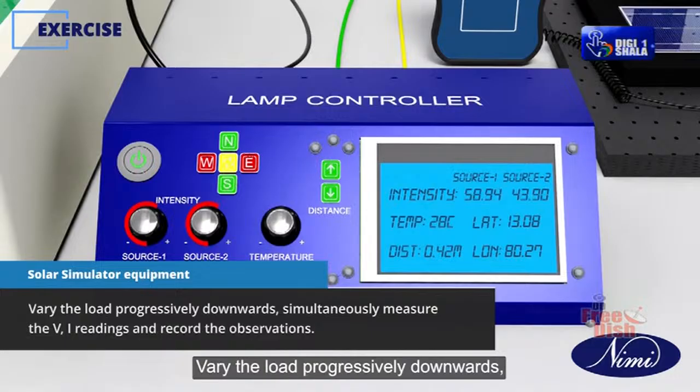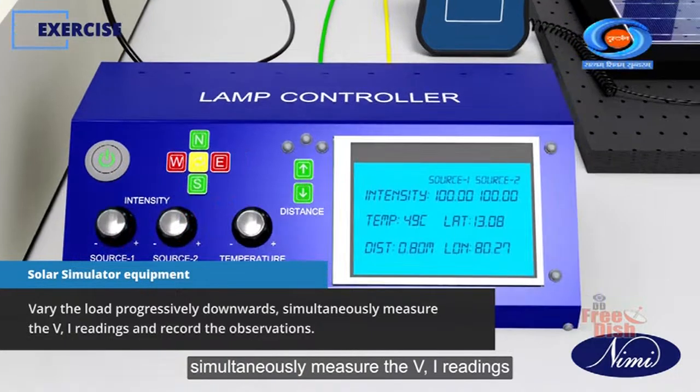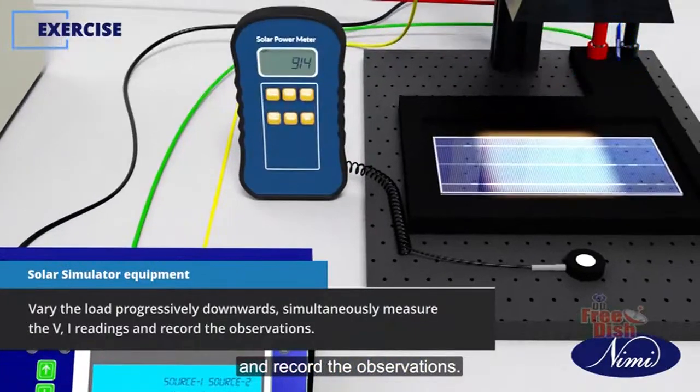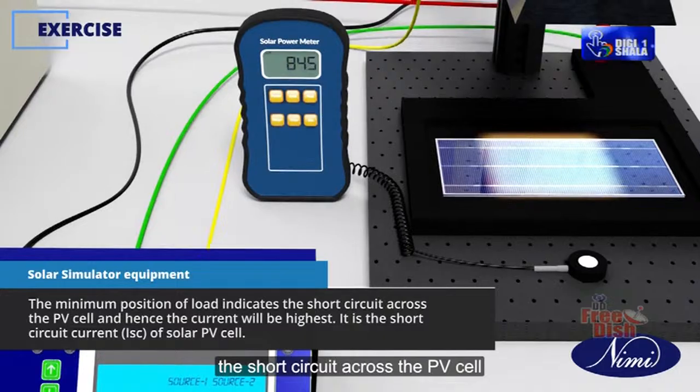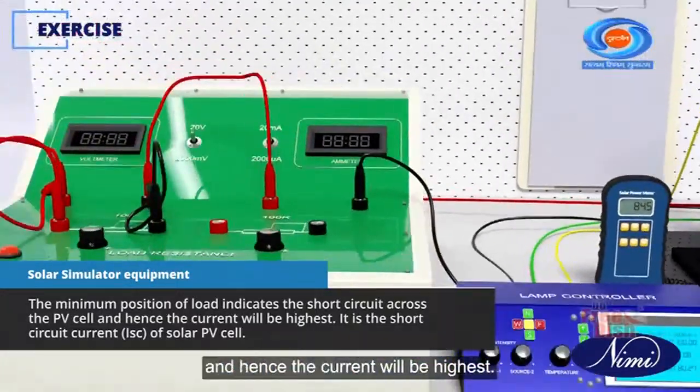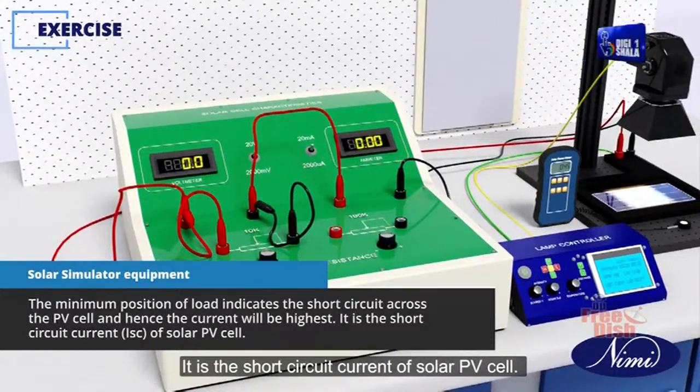Vary the load progressively downwards. Simultaneously measure the VI readings and record the observations. The minimum position of load indicates the short circuit across the PV cell and hence the current will be highest. It is the short circuit current of the solar PV cell.